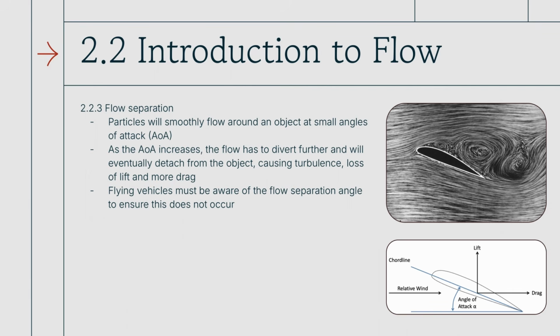And so in this case, that angle was too high, and so the flow was not able to smoothly go around the airfoil. Instead, it kind of just went over the hump and then just was like, what do I do? And tried to fill the void that was there by kind of rotating inwards. And this is less than ideal. You lose all your lift. You don't want this to happen, basically.